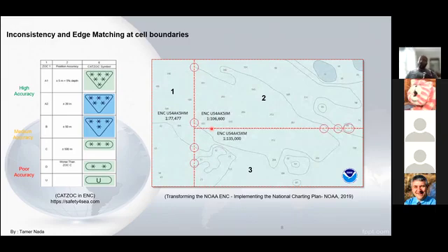And the confidence level for the mariner is very important. So he's always checking the confidence level, at least once while navigating in a new area, to see the accuracy of the chart. Whenever he sees 6 stars like that, or 5 stars, that's high accuracy. Then the accuracy goes down, and whenever it goes down, that's a red flag for him. So whenever he sees some inconsistency like that, it means he has some confusion or some poor confidence in the chart.